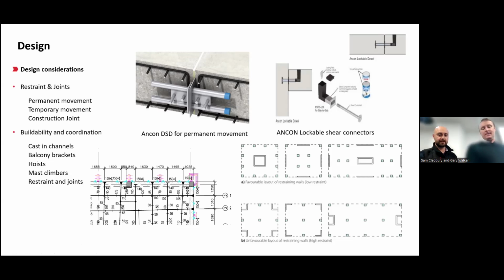Yeah, there's a good little example here, because you can see this triangular shape represents a live end on the drawing. All these little numbers are the profiles of the tendons. So you can see here we've got two tendons. They're matching tendons because they're joined by this link. We've got a live end on this side, but we weren't able to put the live end on this side, so we just flipped it around to the live end somewhere down here, and we've got the dead end which stops short of the slab edge.